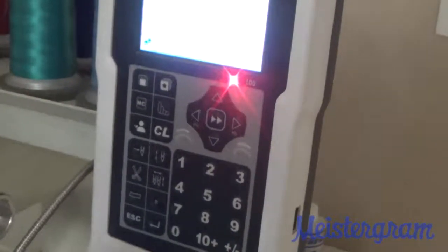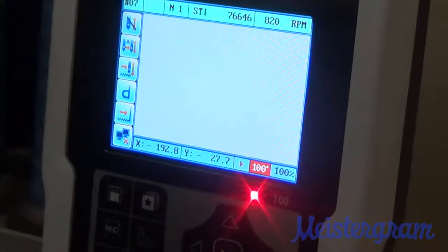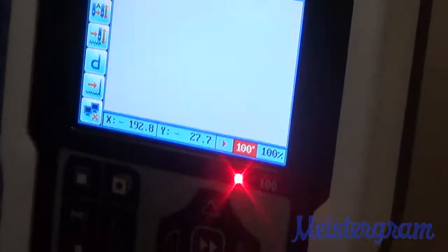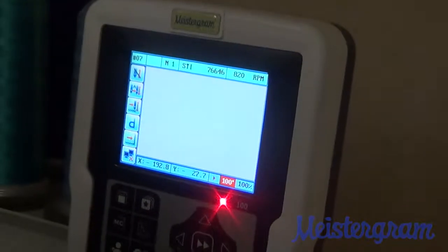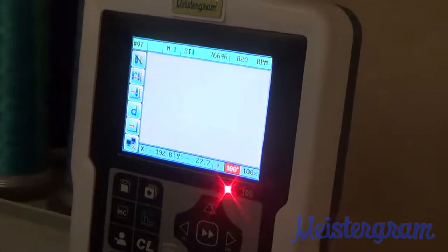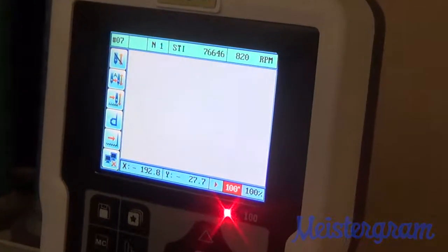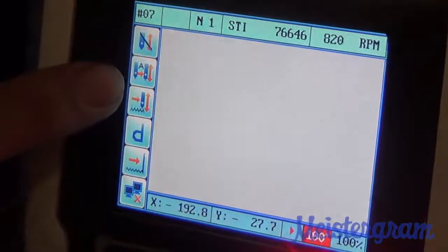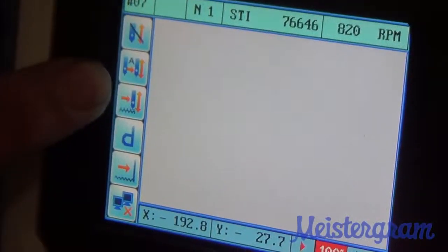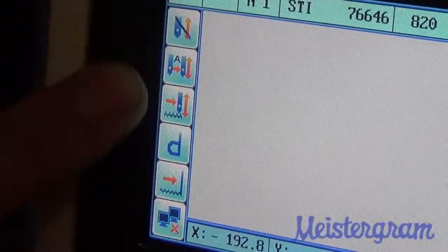The other issue we'll find with the loss of memory is the way the machine color changes. Now, normally designed with multiple colors, the machine will allow you to program the variation of colors, and will automatically make those changes from start to finish. Now, if the machine is not following the color order that's programmed into it while operating, you will need to check the setting for the color change mode. That is shown here on the second icon at the top. Notice we have 2 needles with an arrow pointing right and an arrow pointing up and down. There's an A in the middle there.